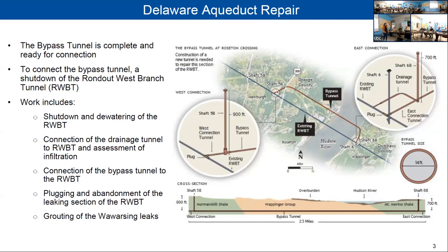That's where the biggest part of the leak is, and that's right where the steel interliner ends. If we had gone a little bit further with the steel interliner when the Delaware Aqueduct was first built, we might not have had this issue. We may still have had it anyway, but the limestone in this area is what we are attributing it to.